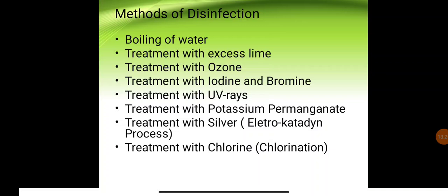The major disadvantage is that the water should be less turbid and low in color, and it is unsuitable for treating large scale water supplies, that is, public supplies. Yes, it is unsuitable because passing UV rays is costlier than the other treatment methods. So it is unsuitable for large scale public supplies, and is adopted for water supplies for private buildings, institutions, swimming pools, etc.